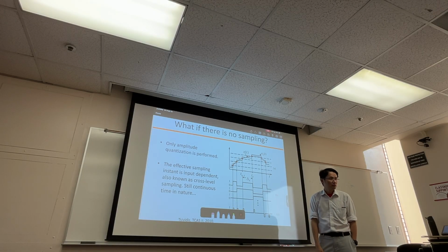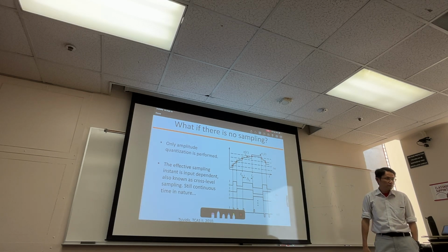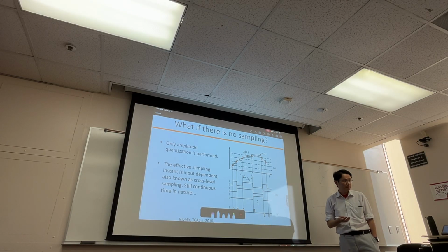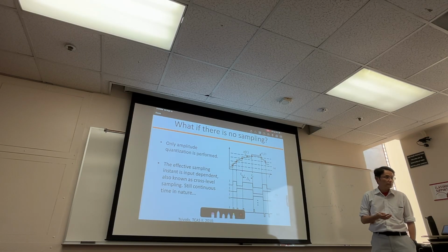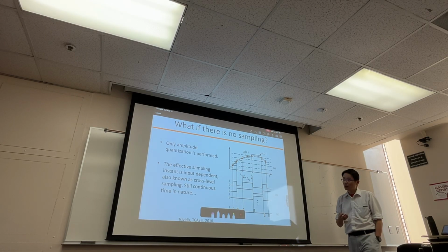Yes. No, but if you do this, then at the same time instant you have to resolve all your ADC bits, right? So you don't have the luxury of sampling the signal and keeping it. You don't have a sampled signal per se. I mean, you don't have an input signal level that you can hold to resolve your bits one by one like a SAR ADC.